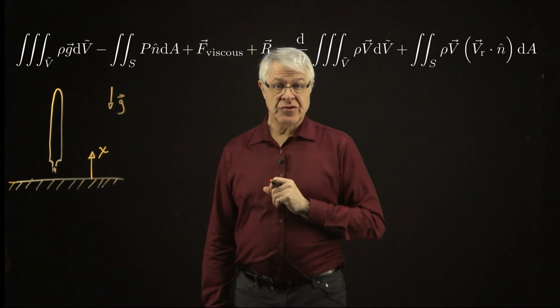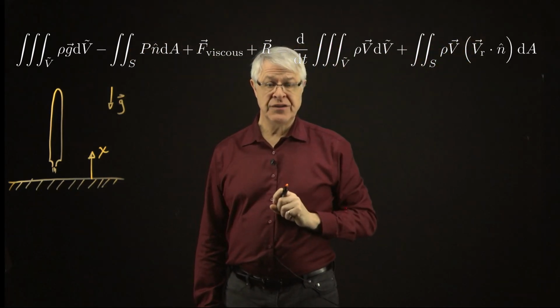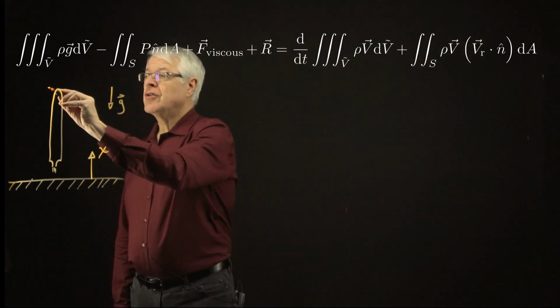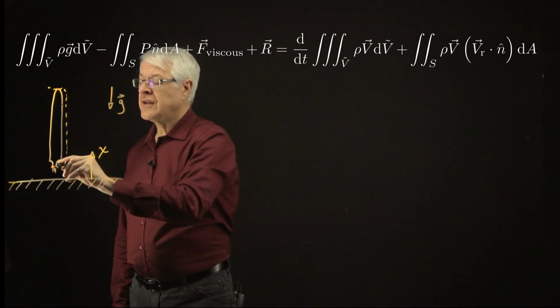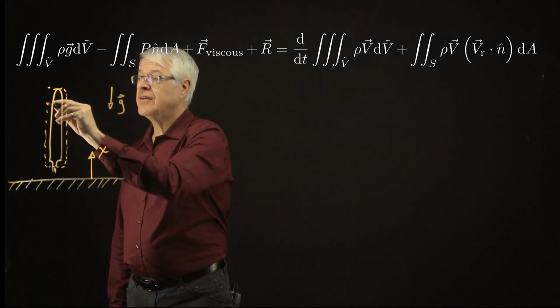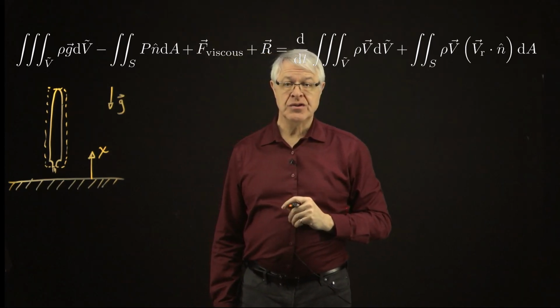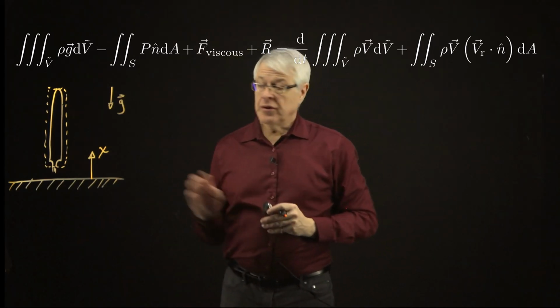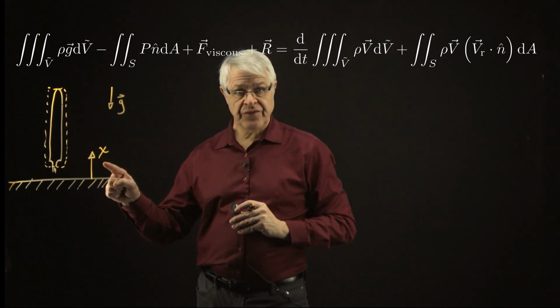Also want to establish our control volume, because we're going to apply control volume momentum balance to this. So the control volume will enclose the entire rocket and cut right across that exit. So that's our control volume that we're applying this equation to. Now a couple of important things about that. First of all, our coordinate system is fixed to the ground.